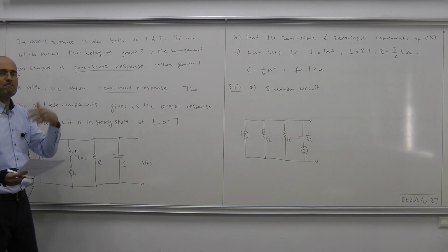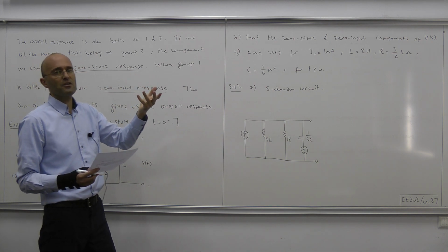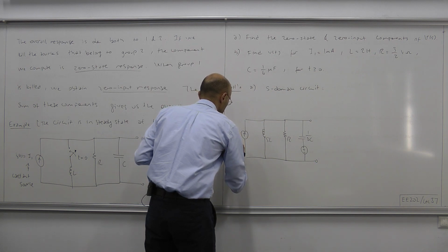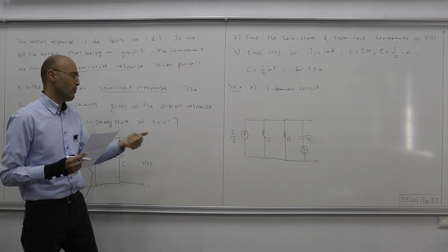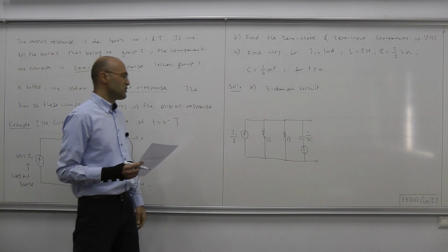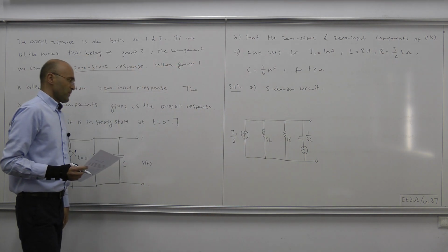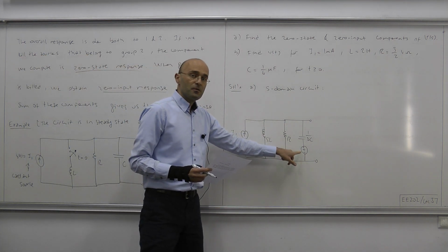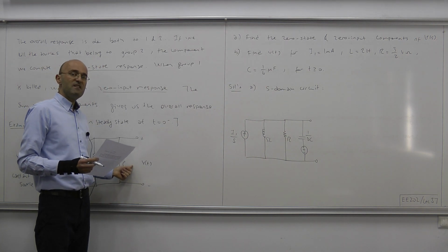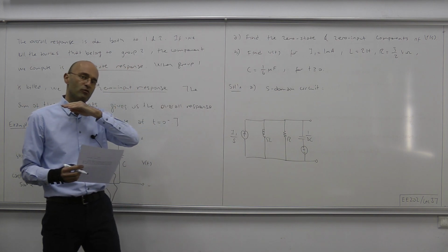Therefore, in S domain, it's the Laplace transform of a constant, and the Laplace transform of a constant is that constant divided by S. So here, I1/S is the S domain representation of this constant time domain signal. As for the voltage source here, which represents the initial condition of the capacitor, it simply equals V0, V0 being the initial voltage of the capacitor, V0/S.